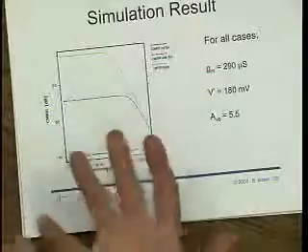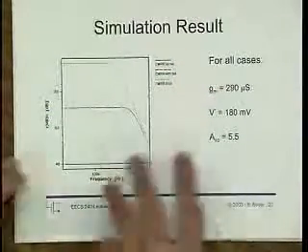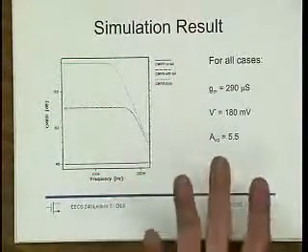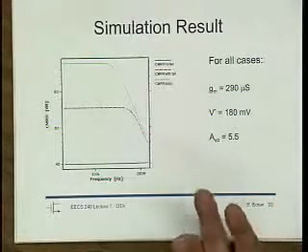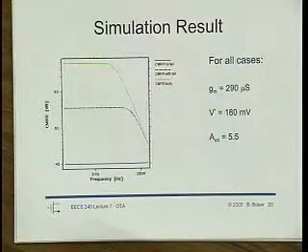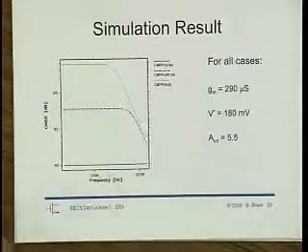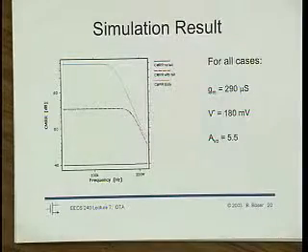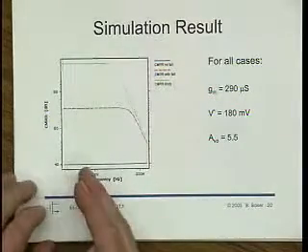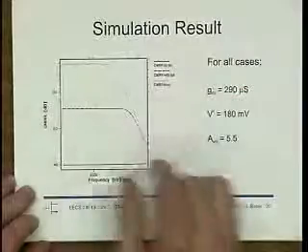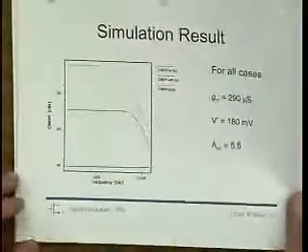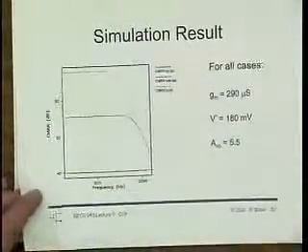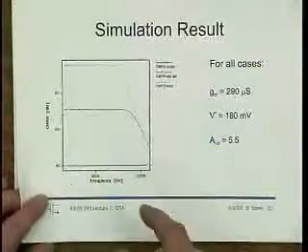It depends on the mismatch that I stick in. I put in a 1% mismatch, so we get 40 dB out. And then with the tail current source, this boosts to about 70 dB, and ultimately we get over 100 with the body tied to the source.